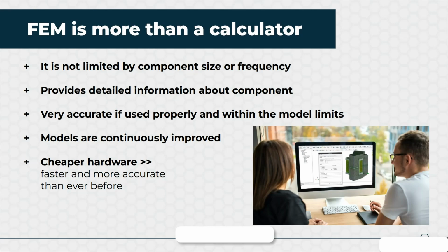So the advantages of 3D FEM are many. Very often, if you are struggling with your design, it's overheating and you don't know why, FEM could be a great tool to answer those questions. Why is my component overheating, why do we have a hotspot, why was my winding burning in some particular area, for example. It can be very accurate. I would say it could be the most accurate method for many applications, for example, for calculating losses in litz wire.